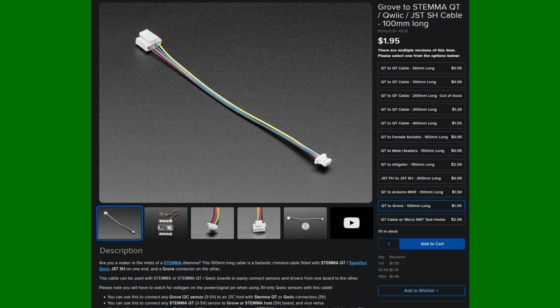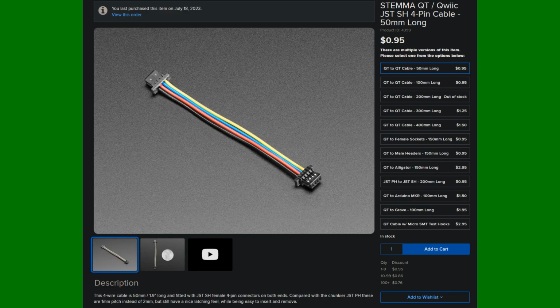Looks like Adafruit has one right there. Boom. So you would be able to buy one of these connectors. You can plug this end directly into the Arduino, and then the other end goes into the sensor. And then if you have multiple sensors that have these Stemma QT connections, which the ones we used in the workshop, almost all of them have this on them.